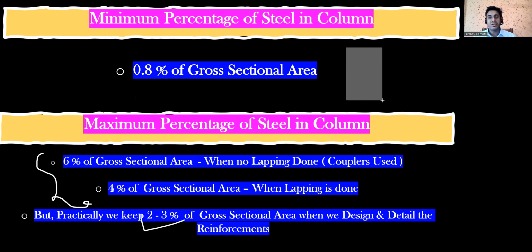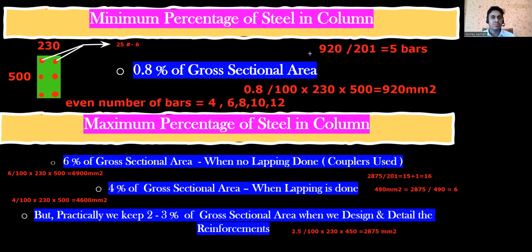Yeah. So like I mentioned, we are supposed to provide this rebar, no? See, now there's one more thing you need to remember. The spacing between these two rebar should not be more than 300 mm. Okay. Should not be more than 300 mm.